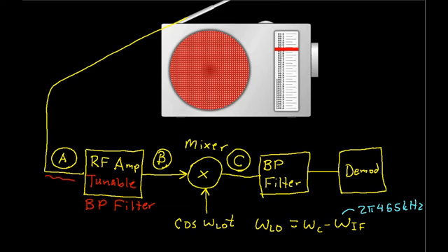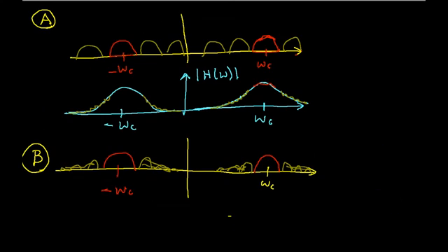This intermediate frequency is different in different types of receivers. So for example, in FM radios or analog television, which doesn't really exist anymore, or other receivers, you'll have a different intermediate frequency. In practice, this is typically set to be what's necessary to make the design work well.